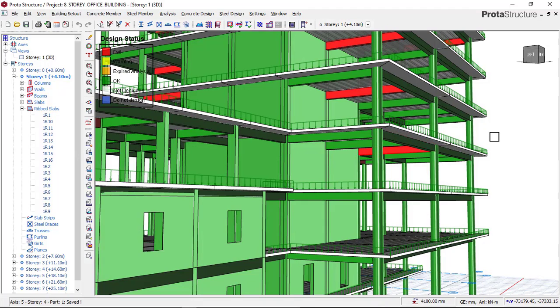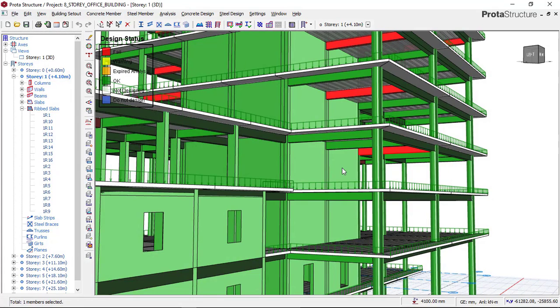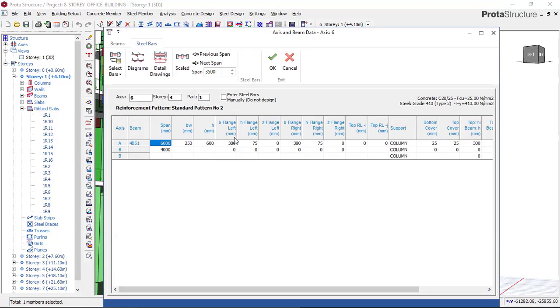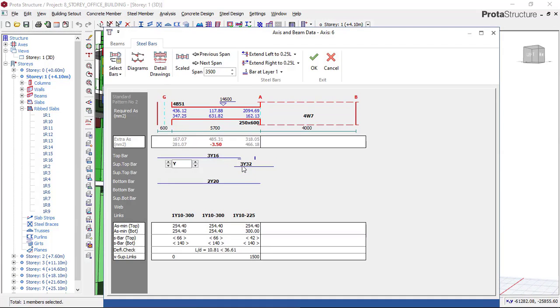You must make sure that all your beams, all your members are showing green before you can start producing your structural detailing. So right now we also check this beam here, and then it allows, okay, click on okay again. The same thing we did here, to be 4 numbers. Now this is okay, but if I don't want it to have a second layer of reinforcement, I can remove this, and if I remove this, it's still failing here. I can make it to be 4 and then decrease. Okay, this is okay, then make it to be 16, and then this is now okay.